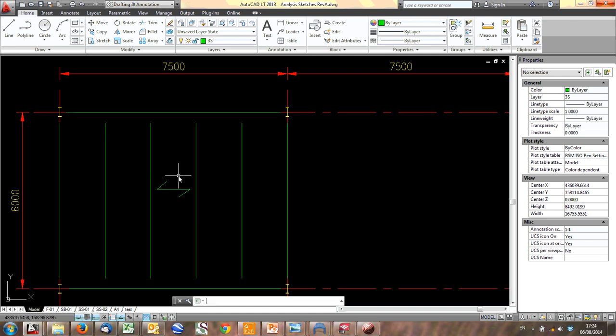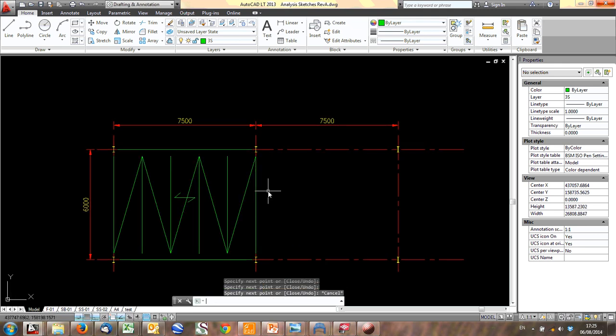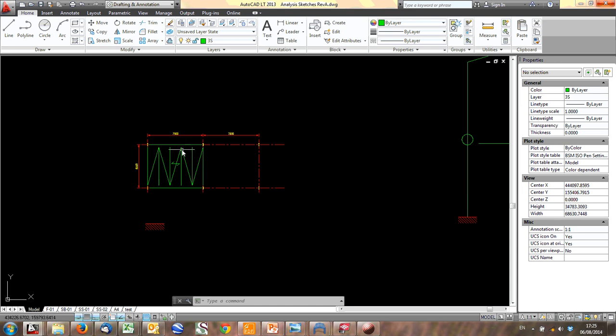Well, you've got to carry the load sideways. So you could even brace this whole floor out. And you can make the floor brace the structure. Something like that. And this then becomes a kind of a truss. And you can use these if there's a horizontal load there. You could actually transfer it through the structure. So there are many ways to carry it.